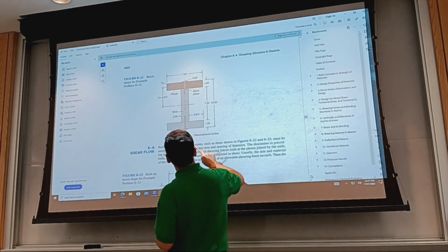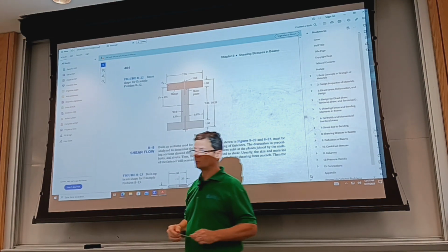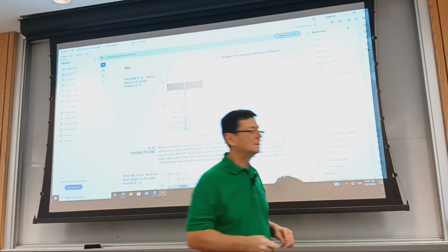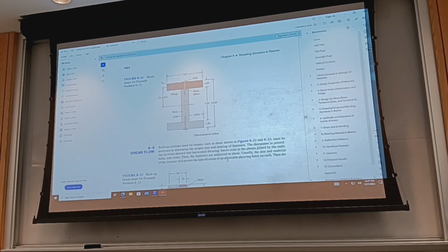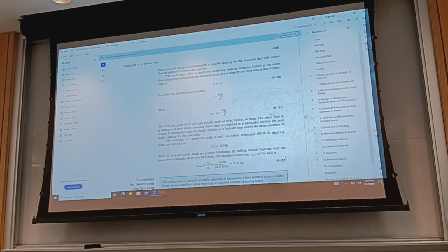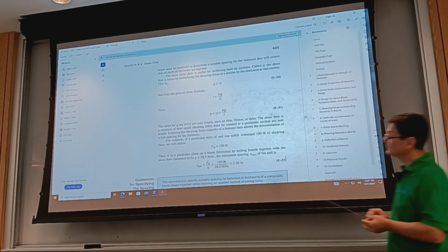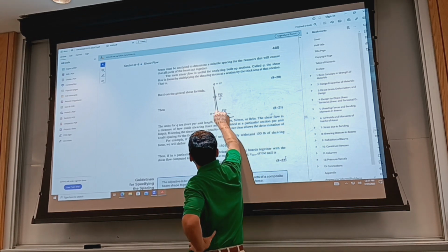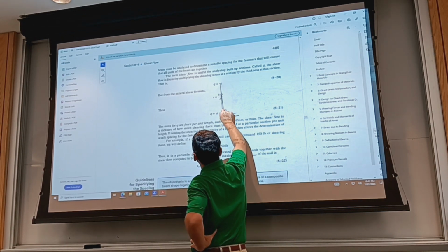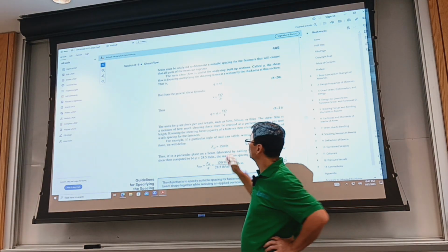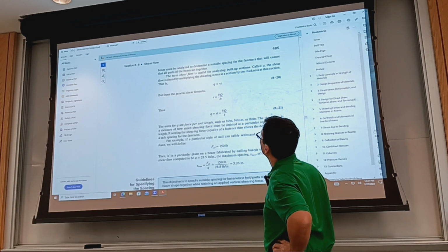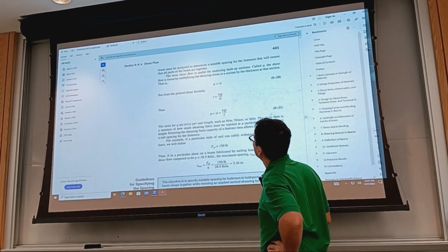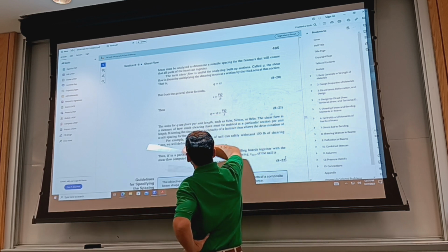If you know that, we'll start for nails with the allowable shear force per fastener, per nail. And we're going to define what we call a shear flow. So shear flow, this lowercase q, has units of force per inch. I take force per unit area times distance, that gets me pounds per inch or newtons per millimeter. So this is the shear flow.